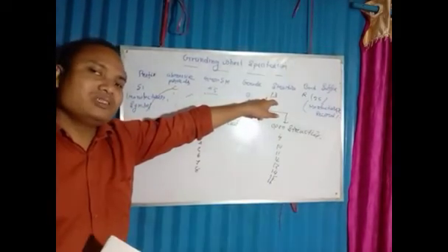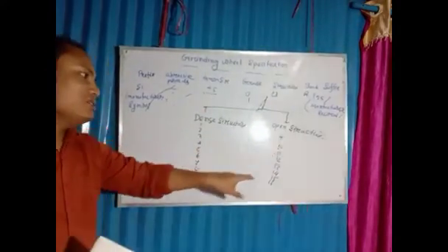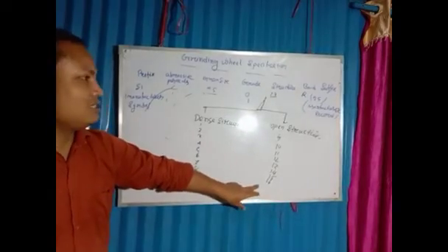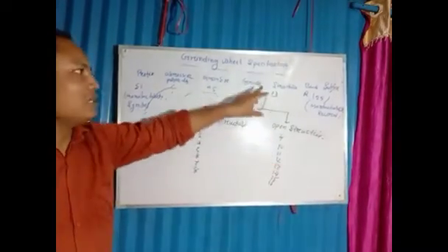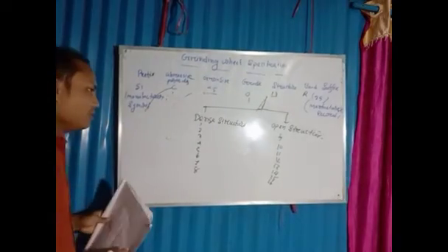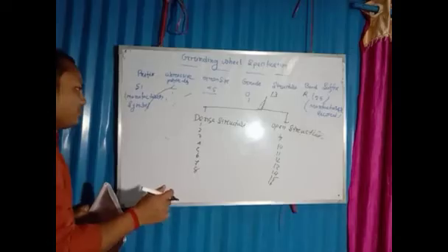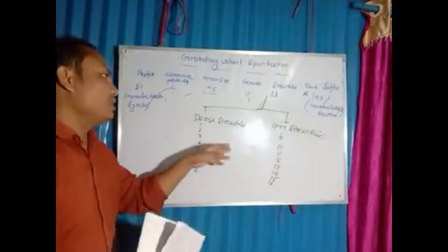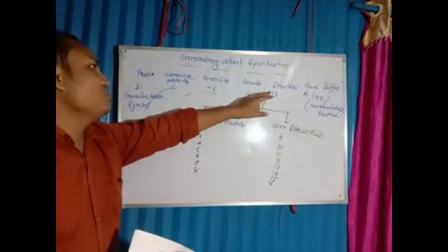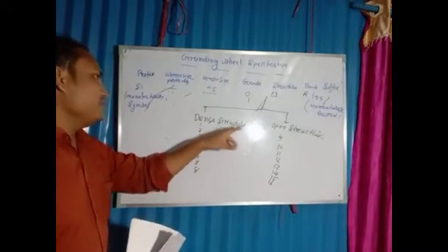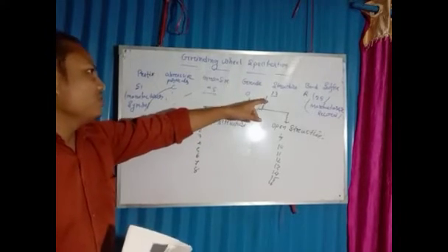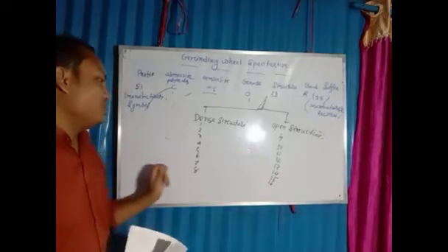Which type of structure is used in this grinding wheel? 13 falls in 9 to 16, so it is the open structure. So by looking at the structure symbol we can understand which type of structure is used.